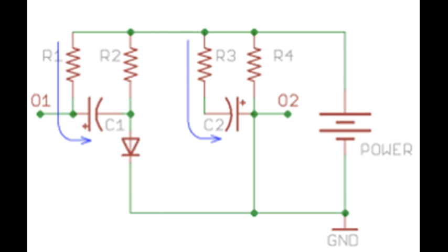Note that since C1's left lead is connected to T1's collector, it will also drop to ground voltage. As C1 is fully charged, its right lead will suddenly drop to a negative charge, minus VCC. This will shut off T2 firmly. Therefore, the circuit will suddenly transition to the following equivalent.